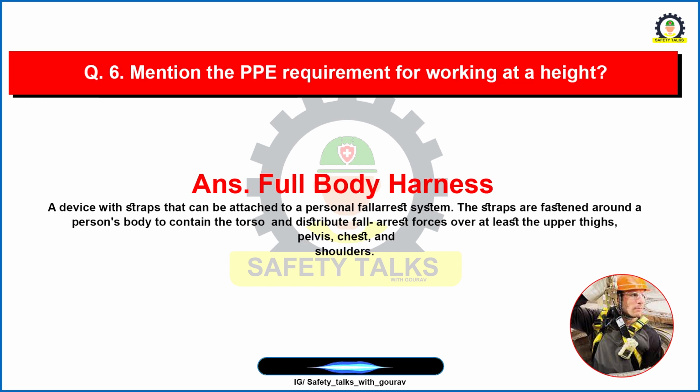The next question goes like, mention the PPE requirement for working at height. What is the minimum mandatory requirement of PPE while we are working at height? Meaning, what particular PPE must be used while we are working at height areas? Okay, so the answer will be full body harness.